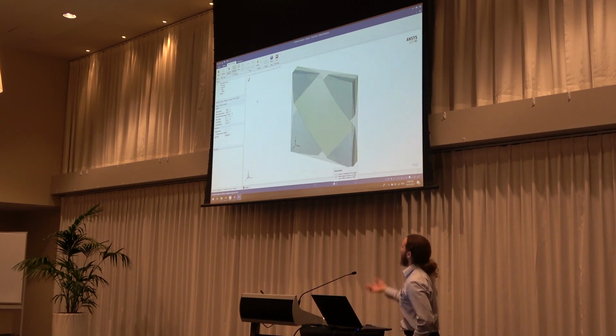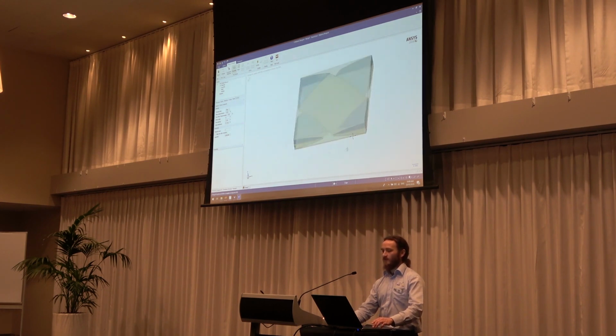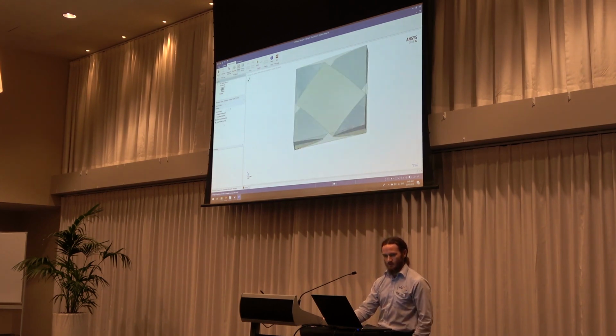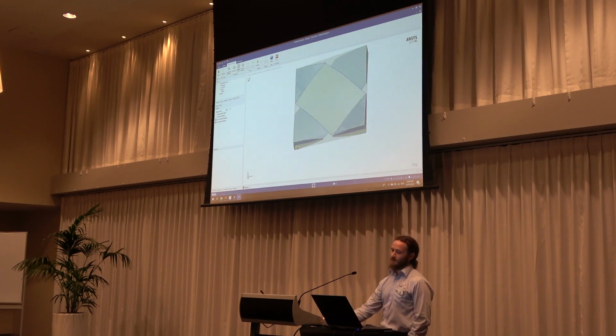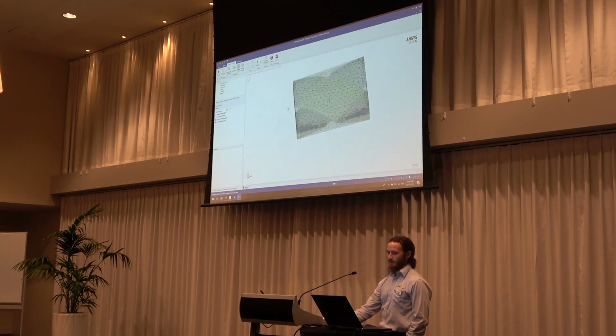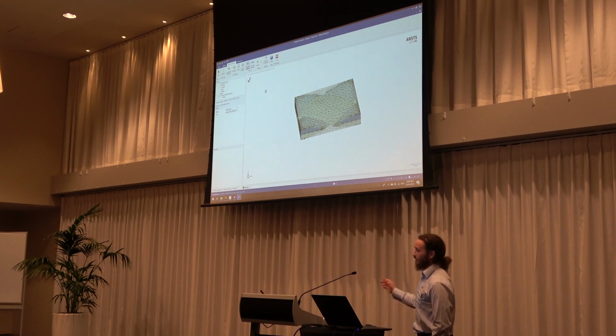So this automatically generates the geometry for that unit cell. So there are a couple of fiber bundles in a unit cell. And then I'll generate a mesh. I'll just give it a rough sizing. The tet meshing is perfectly good, but we can use the block meshing approach as well. So there's our mesh. So you can see it's all stitched together, no contacts or anything in here. Analysis. So we do orthotropic, so I'll just say yes. And now I have constant material properties. So I click that button and hit the tick. So that's basically going to solve this FE model.